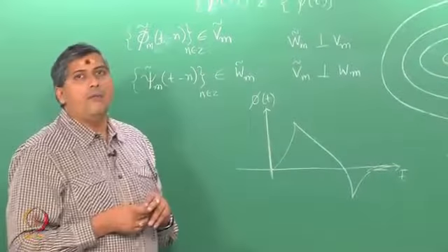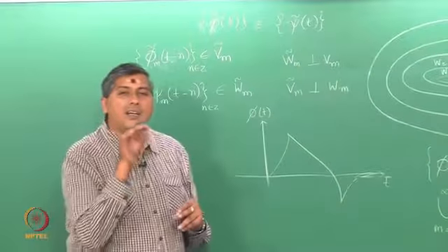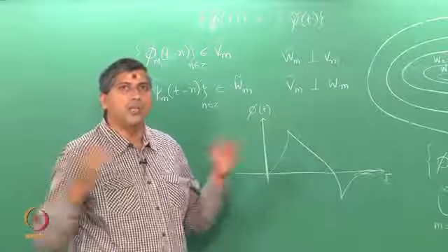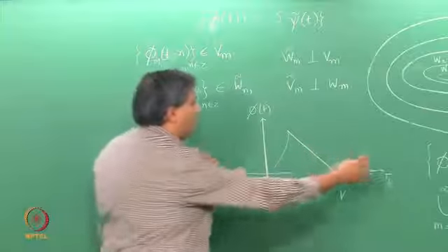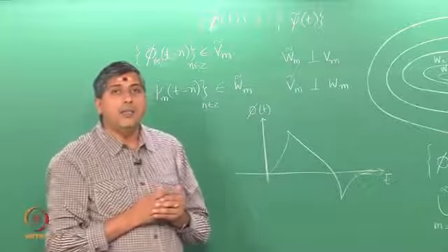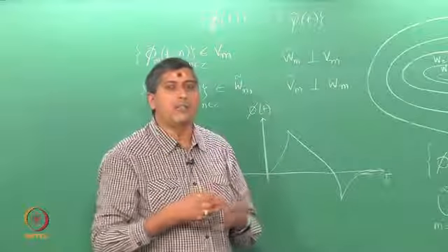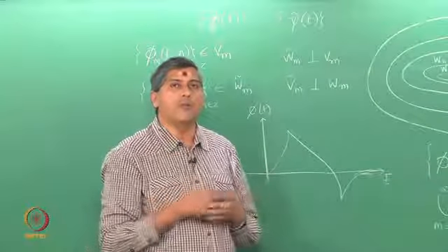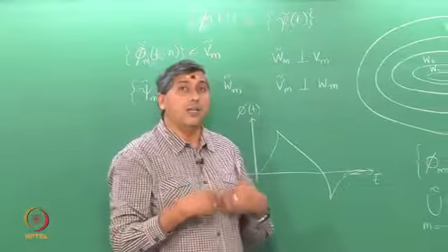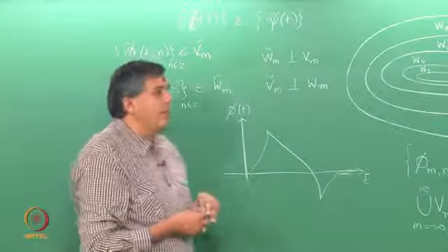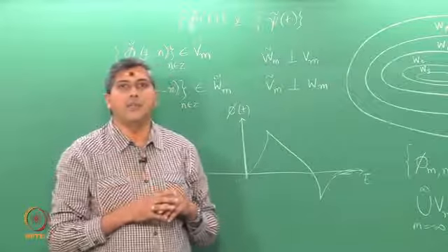With orthogonal wavelets, to design a near symmetric wavelet, you require a much larger support in time, and as a result also a much larger number of vanishing moments, as we shall learn later, and therefore you have to get a more smooth wavelet and so on. Whereas with biorthogonal wavelets, you can nicely design symmetric wavelets.